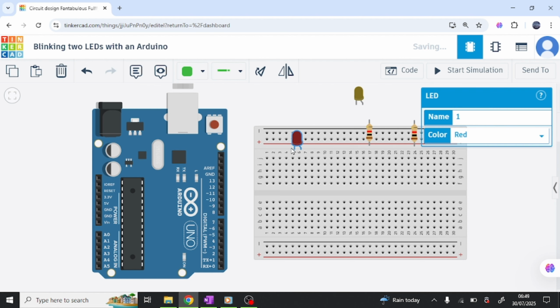we are connecting the positive leg. Now look at this closely. Let me just put this here. Can we see this now? If you put the mouse here, you see that all these lines are connected. Same here, all these lines are connected. Are we together? This is the negative because this is the shorter leg, the cathode. Once you go over it, you will see the name, anode. So negative, positive. So this side should be connected to where?